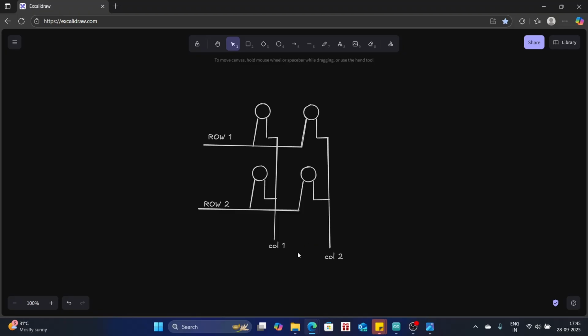So we need to connect them to Arduino pins as well. As you can see here, we require 4 digital pins, and this is just a 4x4 display. Now if we have an 8x8 display, then you'll be requiring 16 pins, right? To avoid this, we will be using an IC called MAX7219, which is a driver IC. The driver IC does multiplexing all by itself.